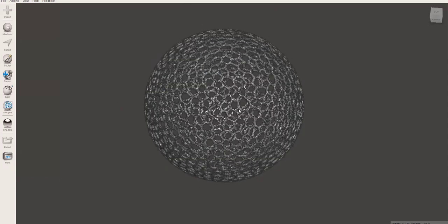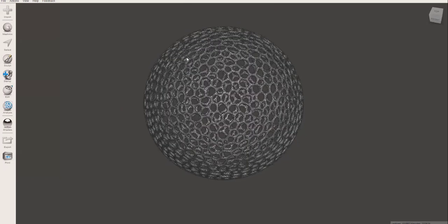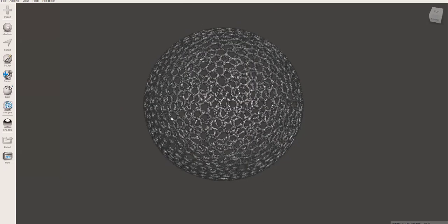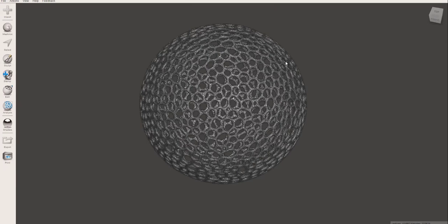There's one important thing as well. If you just want to get one surface of Voronoi patterns, you have to have a surface geometry. What I mean by that is the original sphere we had, that's just a surface, outer surface only. It's not a thin or a filled sphere. In case you have a thin walled sphere, when you get this pattern, you'll see another layer of Voronoi inside of this that is created on the inside surface of the thin walled sphere.